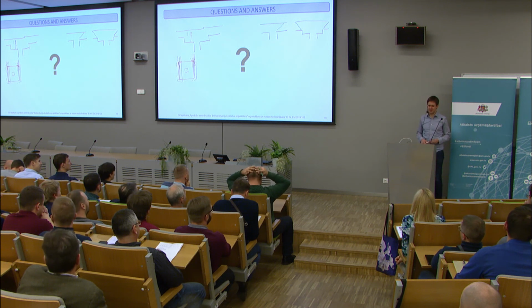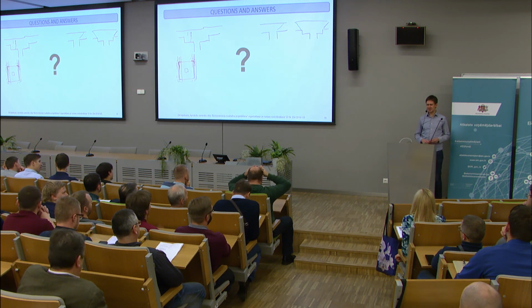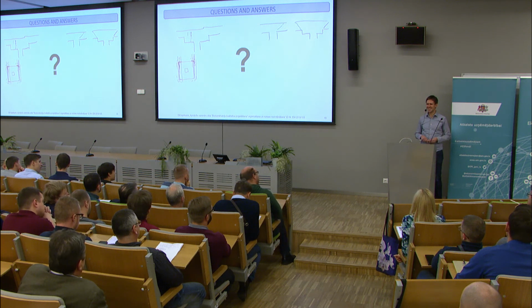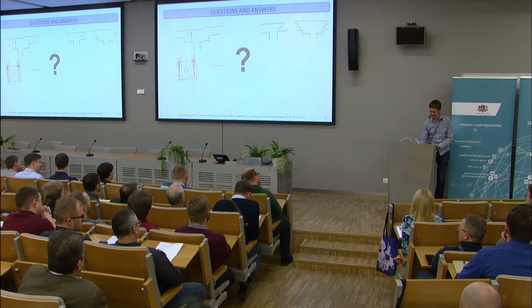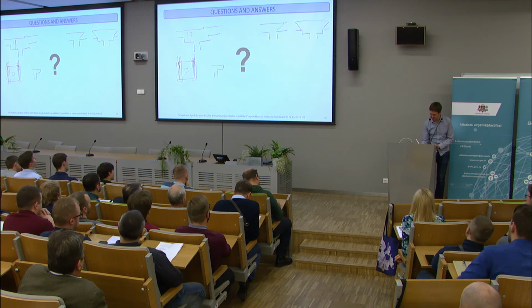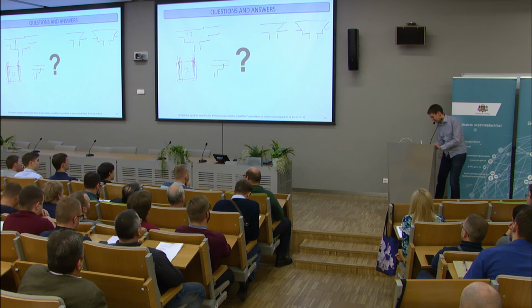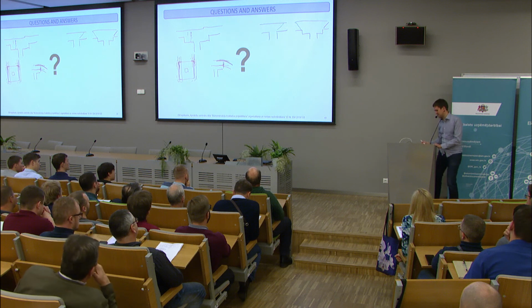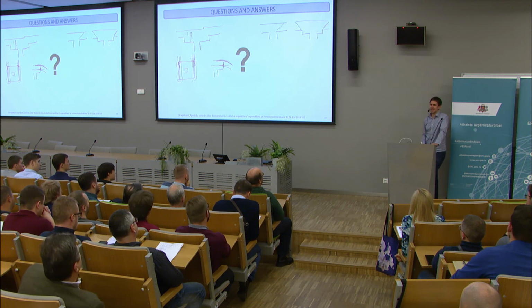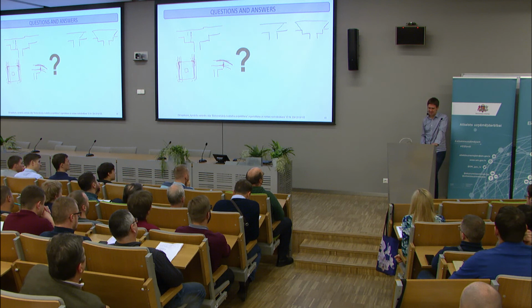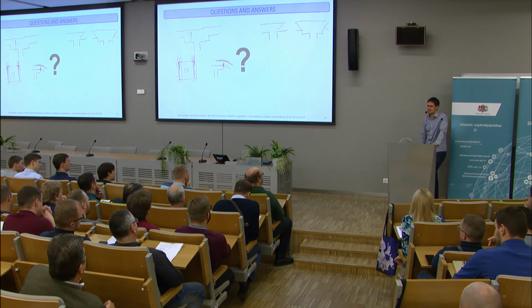But then how far do you dare to go with a plastic design against shear? Because basically it's plastic design. It's just saying that we have a big capital in here, we have a column and a slab on top of it, and we start crushing the concrete in here, but the slab will deform like this. How much can we crush this concrete without actually causing a brittle failure? I think we can crush it to some extent, but it's not very clear how much exactly. Where's the limit? And yeah, the model code limit has been set. It's somewhat conservative.